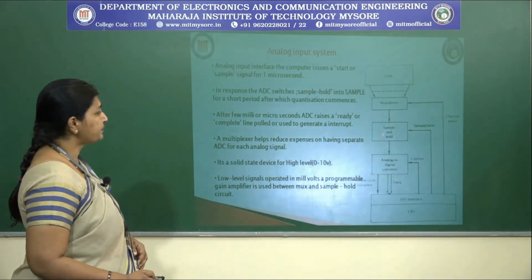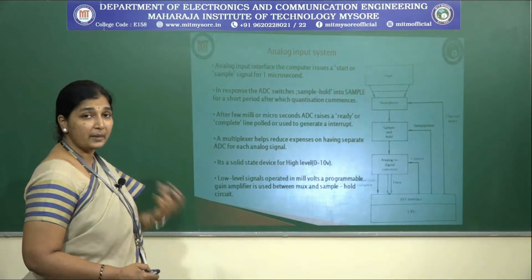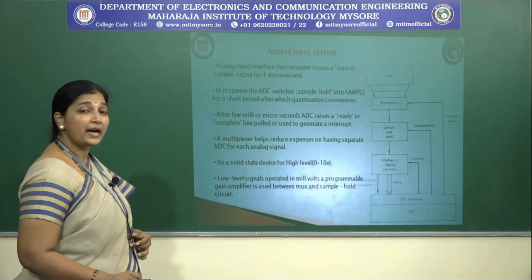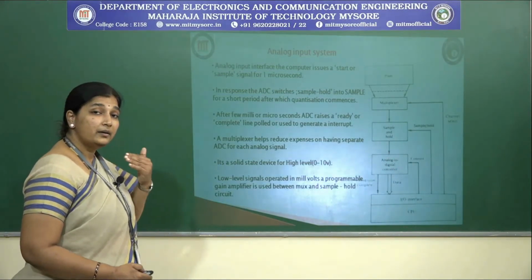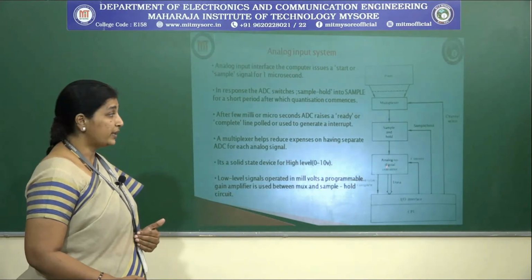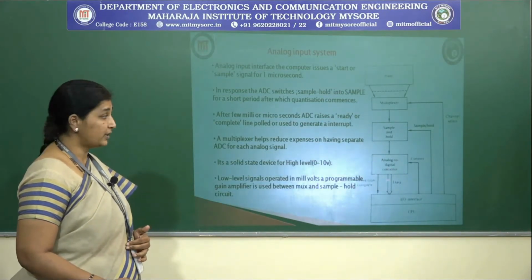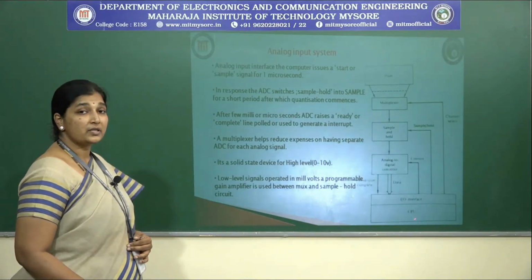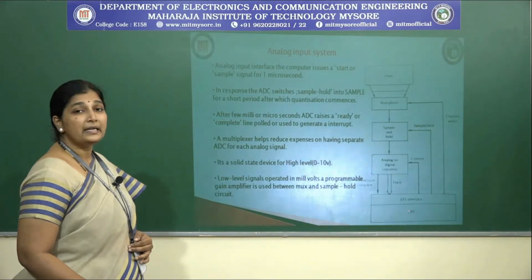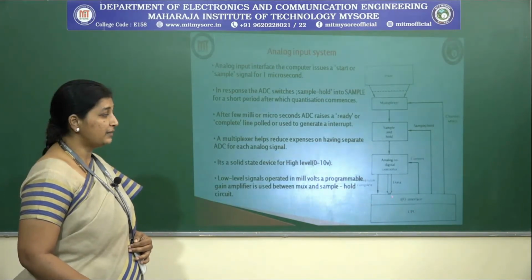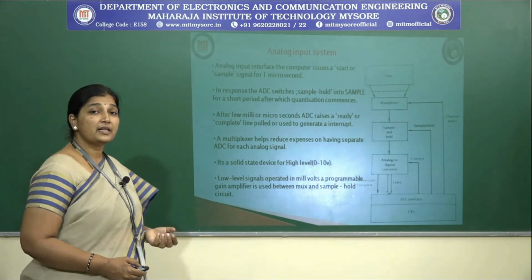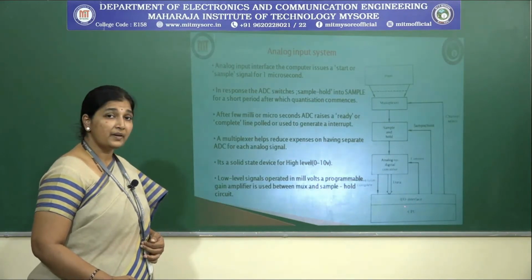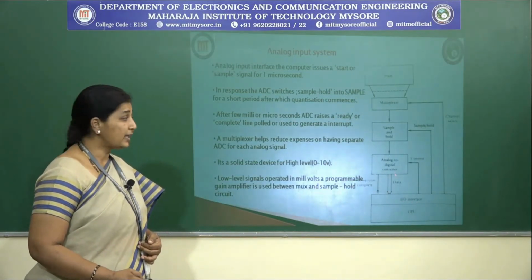So what happens? The sample and hold circuit will have all the samples which have been discretized, and you have analog signals which are actually discretized, with a quantization level fixed before it reaches your analog to digital converter. This digital converted signal will be sent to the central processing unit through the input output interface. At this interface, we would have already fixed the level for ones and zeros. So the input for these IO devices will be zeros and ones, that will be the data.